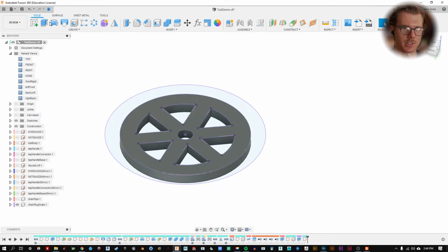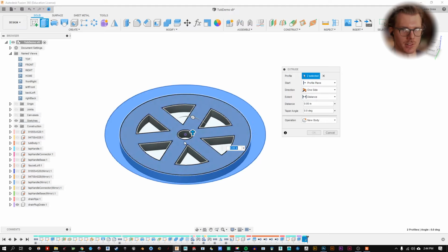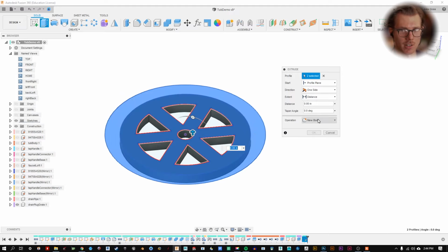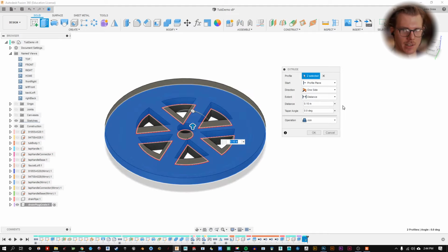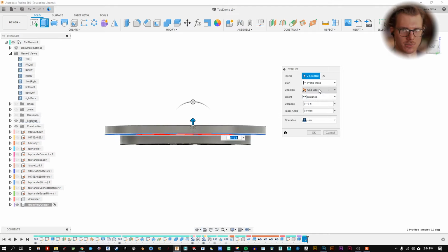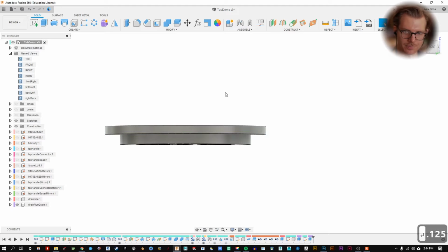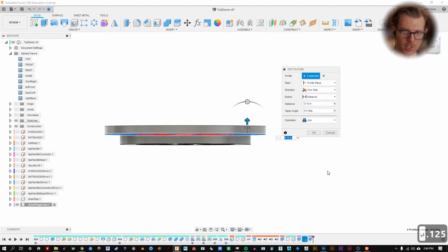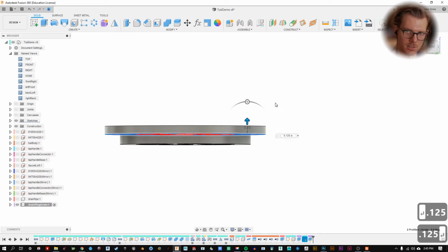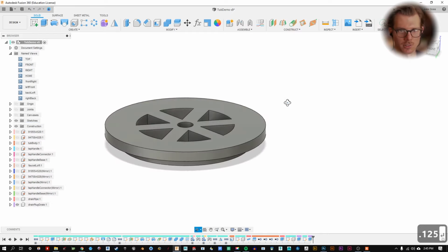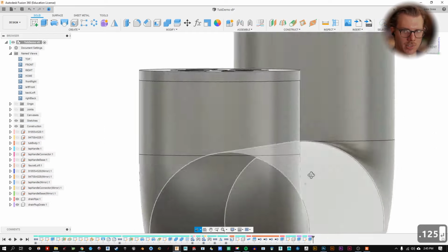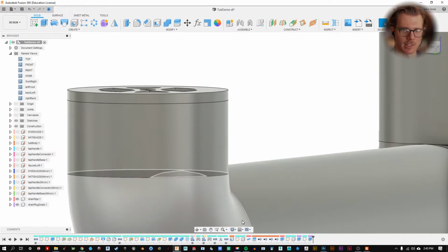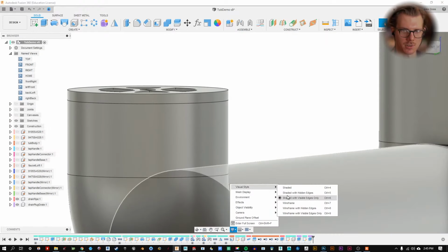And what we want to do is extend those up together. So we are going to now make this join this component, and let's make that another 0.125 up. Whoops. Hit enter too soon like me. Cool. Let's look at that with the pipe, and maybe we can look at it with our X-ray vision and just kind of see what's going on.